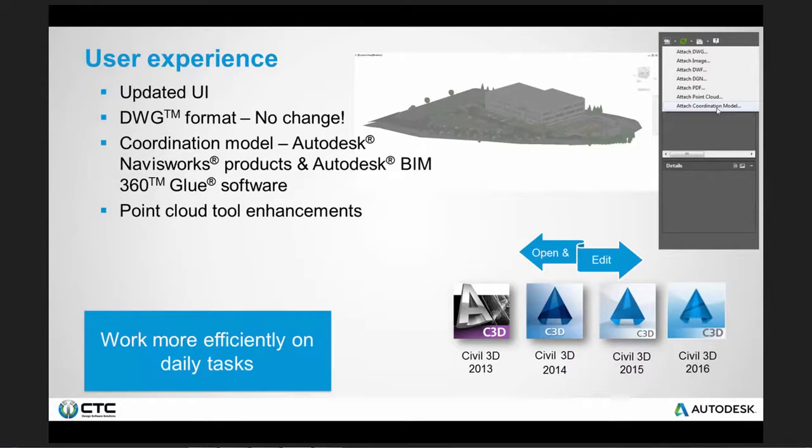Those were there last year, but there's some enhancements again, including creating a surface from a selection of point cloud data. We can trim down or filter down the amount of points showing based on a spacing. So it's not a percentage, but we can put in, eliminate points that are closer than 1 foot or 2 foot or half a foot. It's a nice way to filter down the data. We have cropping options for the point cloud information, and we also have some intelligence there that will eliminate vertical spikes such as trees or power poles or perhaps a bird that was caught in the point cloud.